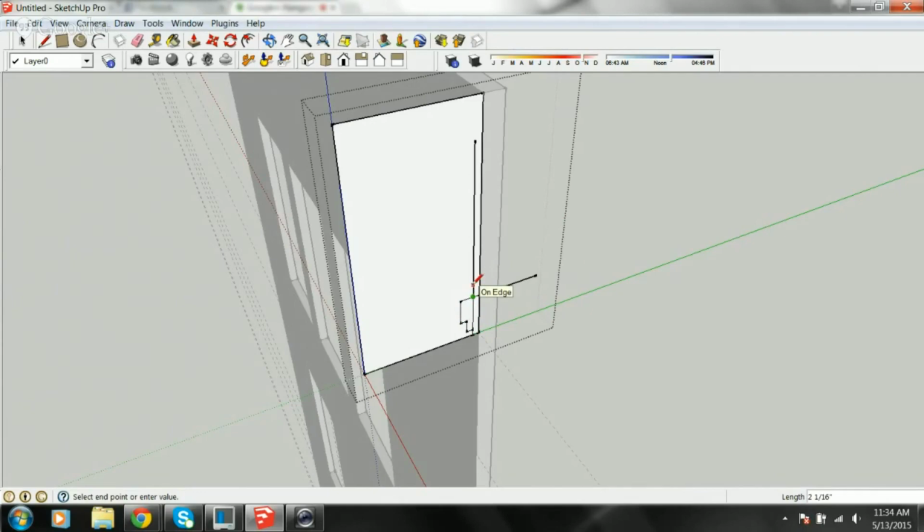So I'm going to come up an inch off of that, and I'm going to come down here, select that. There's my angle. I hit spacebar to get back to my pointer. Okay. And then I click on it, and then I hit the delete key. I just like to keep things clean while I'm drawing if I can. Okay. So now here we go.